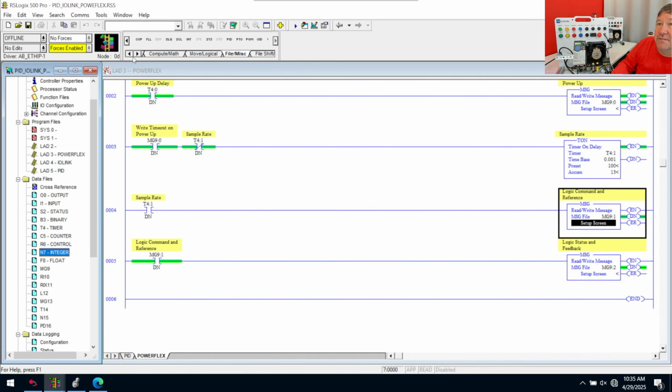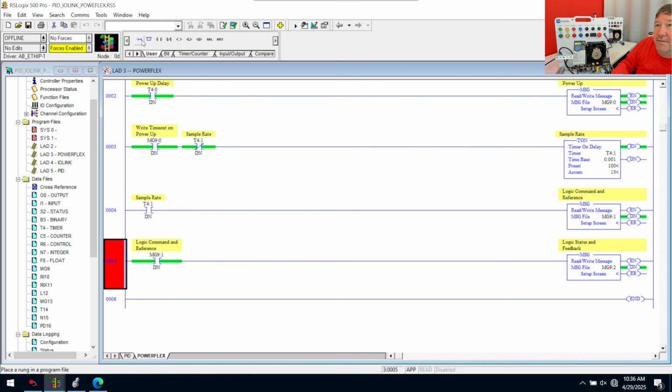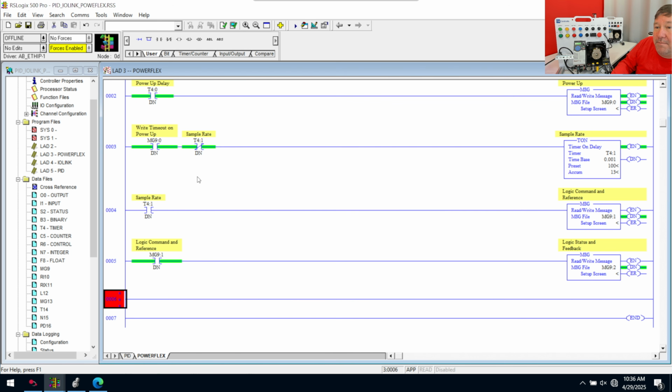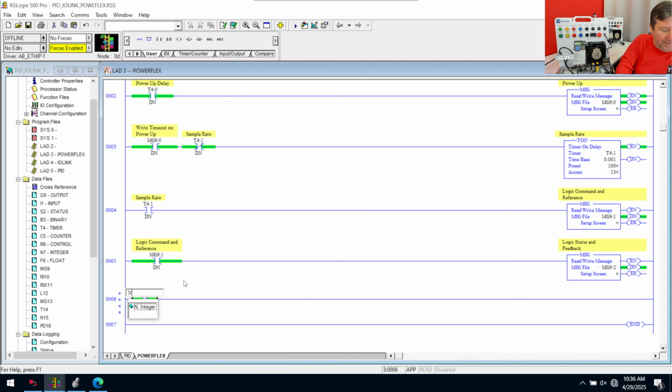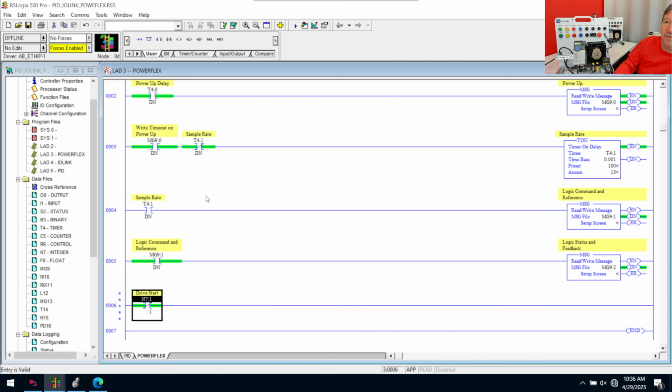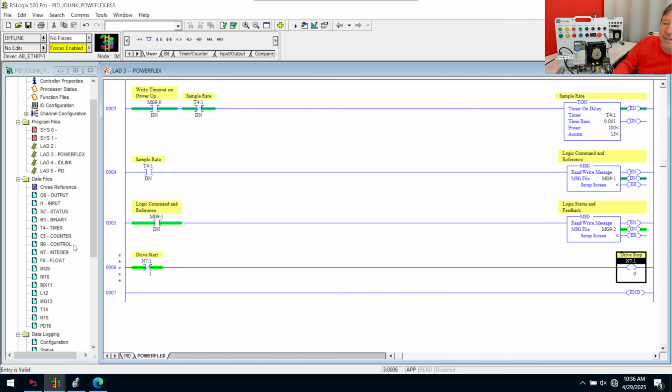But one, I want to go ahead and put those in just like we had them in the other program. You probably already have them in yours. I just don't. Honestly, I was moving on to another video when I realized we could learn about PIDs right now. And I was like, well, no, we need to go do that. So in that one, we had to go look for a 0, and it was for N7:1/1, which is our drive start. And we put an output energize of N7:1/0, which is our drive stop.